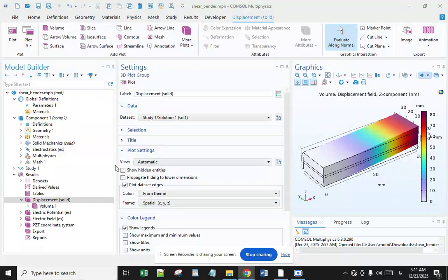As piezoelectric actuation is applied in practice to different kinds of structures, it is worthwhile to investigate the effects of structures' stiffness on the performance of the actuator. Therefore, an analysis of this effect was achieved by evaluation of beam tip displacement through piezoelectric actuation for several structures stiffness ratios.